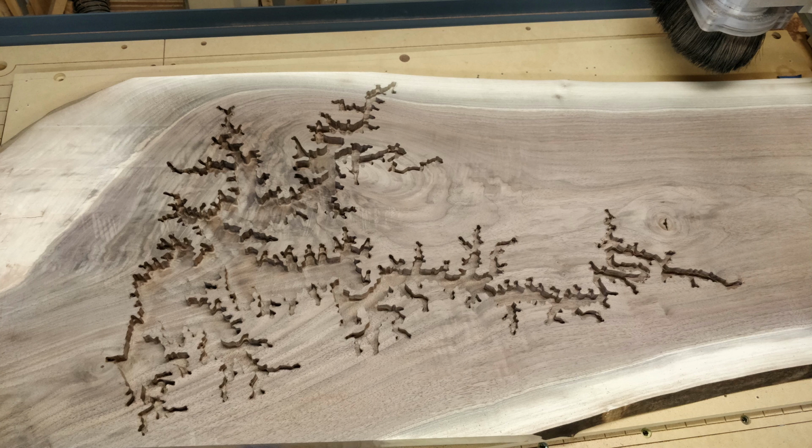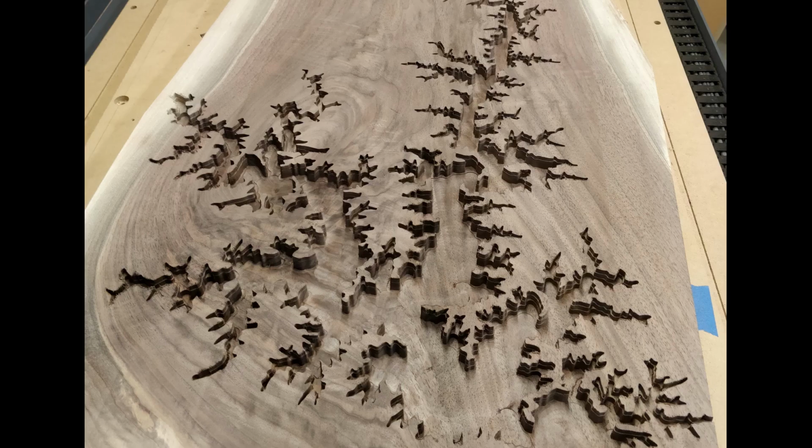I chose to only go down to the 10 millimeter, the first pass depth, rather than completing the full 17 millimeters. It took 2 hours to do this, and I really wasn't going to invest the extra 2 hours to complete the second pass when we'd never see it, and it might add air into the epoxy. You can see the level of detail here. It's quite impressive as you go, and I have a picture of adding the 1 millimeter bit as well.